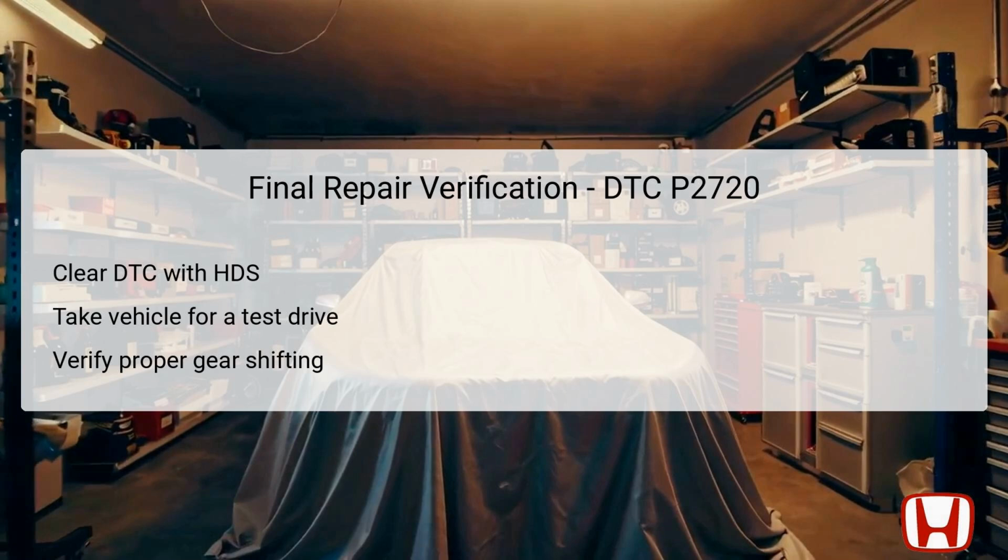Start by clearing any DTCs stored in the system, using the Honda Diagnostic System, HDS, to reset the vehicle's computer. Next, it is essential to take the vehicle for a thorough test drive under varied conditions to ensure that the repairs made were effective.